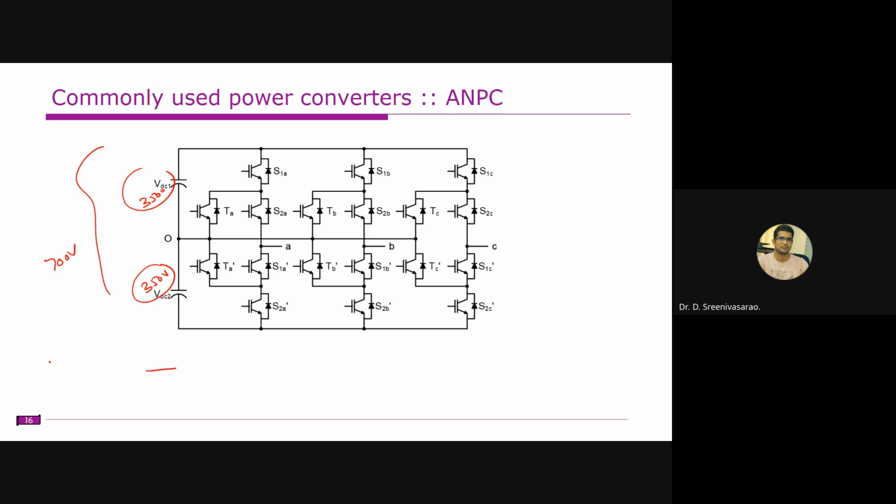So here we need to use two PI controllers. This is the sum of the two DC link capacitors, VDC1 plus VDC2. The sum is compared with the 700 volts here. All right. Let us assume you will get one ID star here, some small value, and we have some minor loop here. So this is another loop.